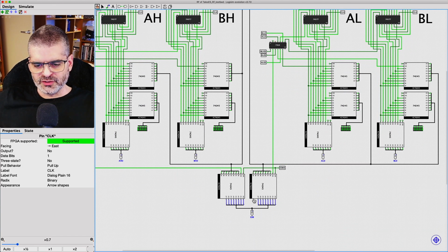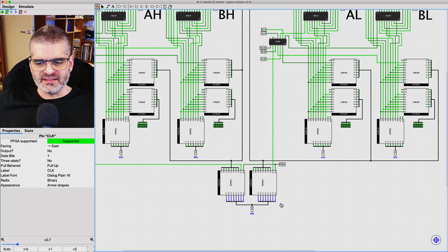We can now see if we are driving or receiving a value from the external data bus correctly. I didn't put any dip switch or LEDs, but it doesn't matter because we can look at the color of the lines to see whether they are 1, light green, 0, dark green, blue means floating, undefined, and red means a bus conflict or a line conflict. So it's blue now because we're not driving any value out to the external bus, and there is no value being driven to the external bus from elsewhere, so it's all floating, it's undefined.